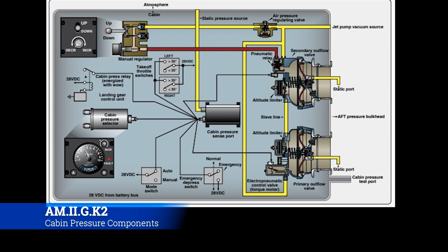So effectively, the valve opens and lets air out, or can close to help bring the pressure back up. Effectively you're turning it on and off. Imagine a bathtub, right? The bathtub is like your cabin pressure. What you want to do is close the outflow valve, or plug the bathtub up, and turn the faucet on and let the water build up. But at some point, if we get too high, the water's going to spill over. So what we want to do is pull the plug so that as new water comes into the bathtub, old water goes out, and we maintain a certain rate.